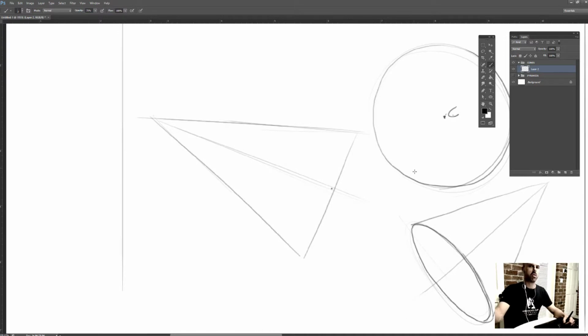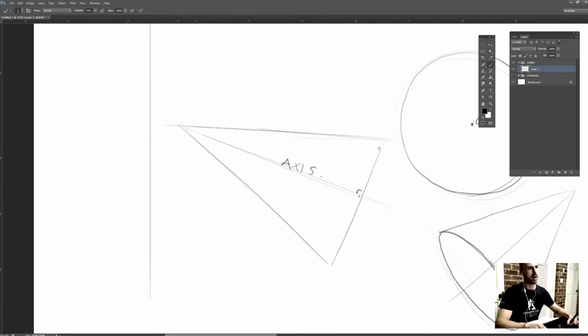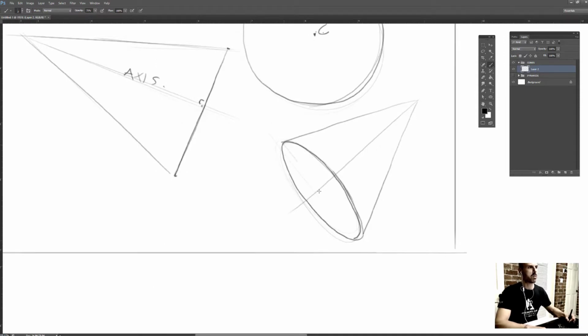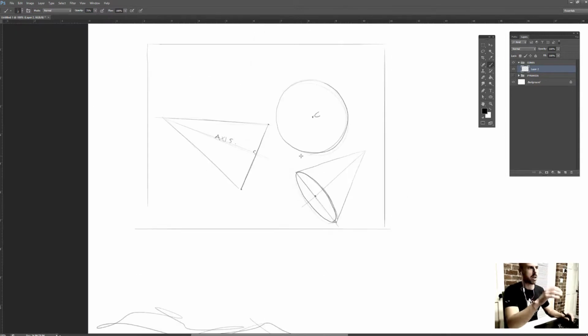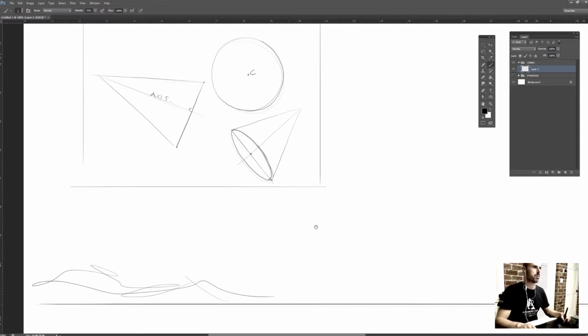So again, for the vertical cone, all you need is basically just to identify the center. When you sketch horizontal cones, again, what we did was to sketch the axis first, 90-degree line, and then I have just started the major axis of the ellipse that is going to drive how to sketch the position of the ellipse, basically.